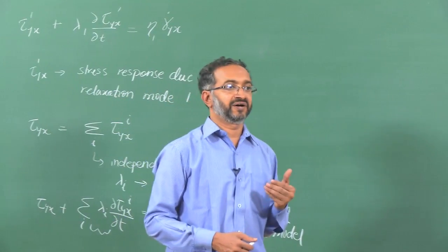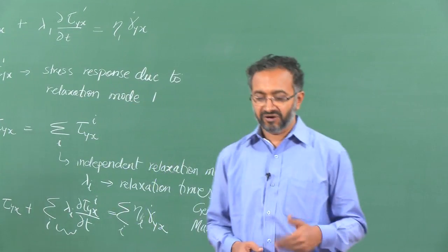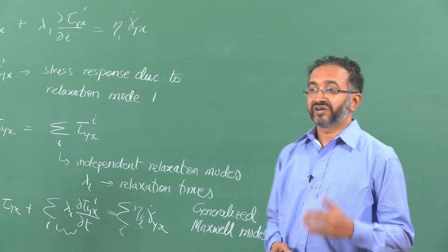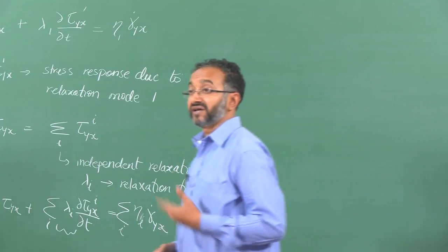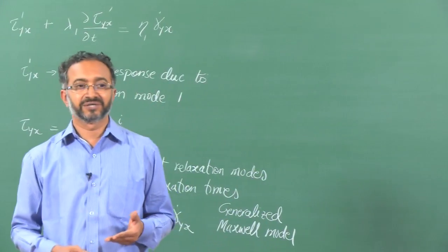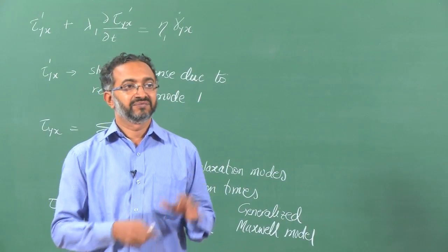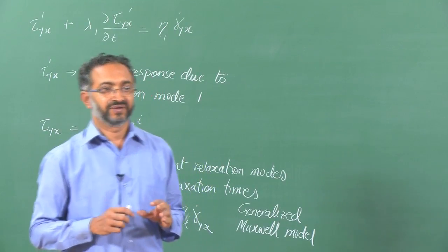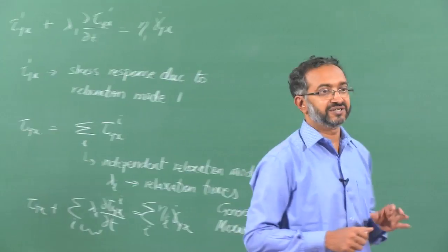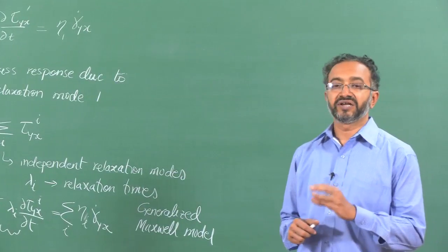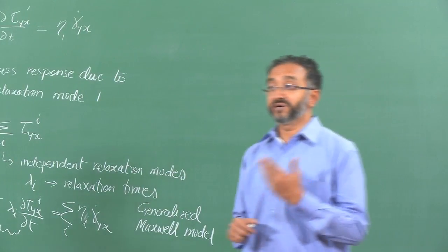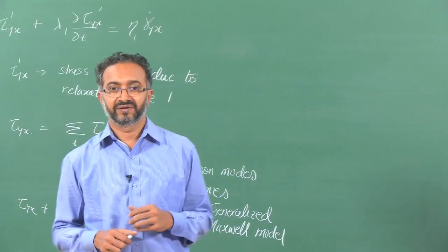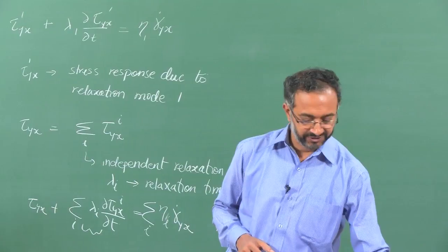The idea of doing oscillatory shear or a stress relaxation experiment is to try to capture what are the relaxation modes which are there in the material and try to explain both the oscillatory shear and the stress relaxation modulus of the material. So, the of course limitation is that we will only have to work with small deformations or not perturb the material very much away from equilibrium. So, under those conditions this is quite useful.